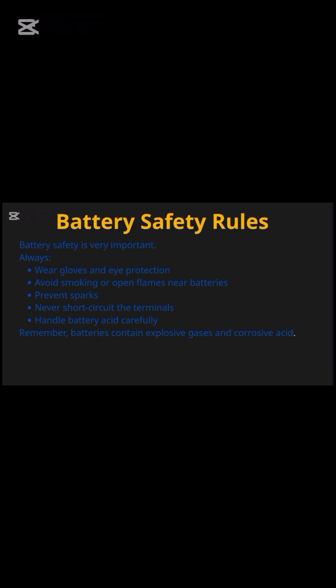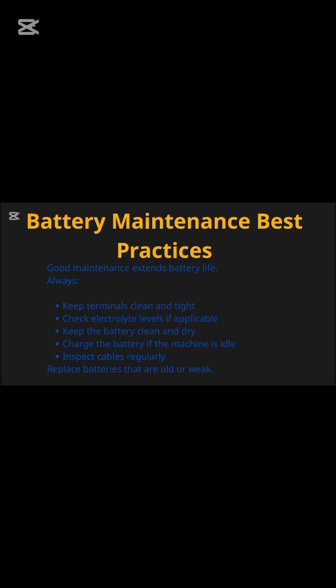Avoid smoking or open flame near batteries. Prevent sparks. Never short circuit the terminals. Handle battery acids carefully. Remember, batteries contain explosive gases and corrosive acids.